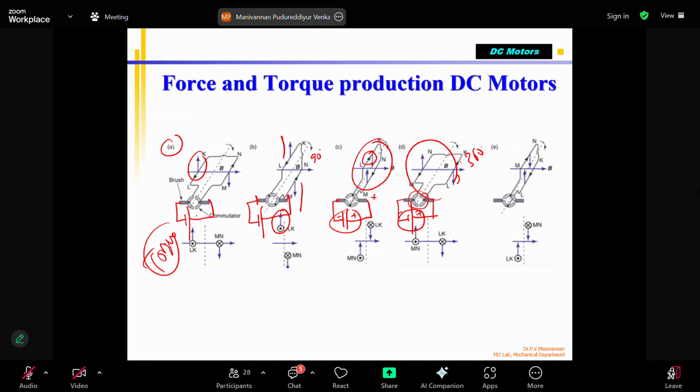Yeah, you can see here. From the battery, wires are coming, touching the brushes. This is rotating. The commutator gets the power from the brush. The brush will have a spring loader, so it will be pressing against this one. So there's a constant rubbing. Because of that, the brush as well as the commutator will get worn out. Not within 1 day or 2 days, but slowly within 6 months or 1 year. After 1 or 2 years, depending on how long it runs, you need to change the brushes, because they are generally made of carbon material. The commutator also will get damaged after a few years. So sometimes you need to change the entire assembly. Correct? That means physically you have to remove the armature, completely open the motor on one side, and remove all those things.